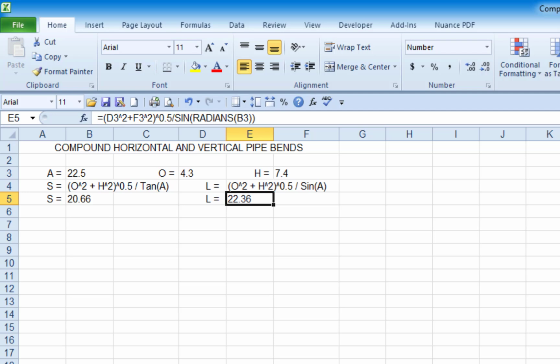The distance between the centerline PI and the pipe insert point for a 6-inch bend is approximately 0.4 feet or 0.8 feet for the two bends. The required length of pipe between the two bends would be 22.4 minus 0.8 or around 21.6 feet, which is a greater distance than a standard length of pipe. Using a pipe length of 19.5 feet, which is a standard length with a bell end cut off, the distance between centerline PIs of the two bends would be 21.3 feet.